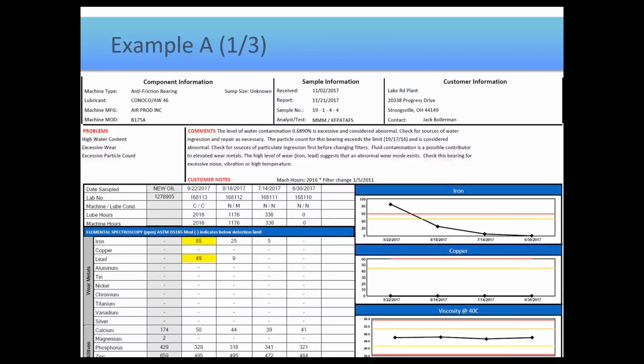You put the dipstick back in, you tighten the cap on, you replace the breather, whatever it happens to be. Here's my next question now in this hypothetical situation. If you spot something that was obvious and you correct it, what do you do after that? Well, there's kind of two schools of thought. Some people think you should resample the machine, and some people think you should change the oil. So let me address both options.